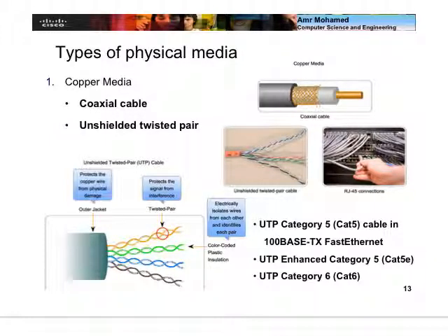There are certain differences between coaxial and unshielded twisted pair. Generally speaking, thick wires tend to have a wider frequency range in terms of the frequency of the signal that goes through the cable. If it's thick copper, then the frequency range becomes wider.